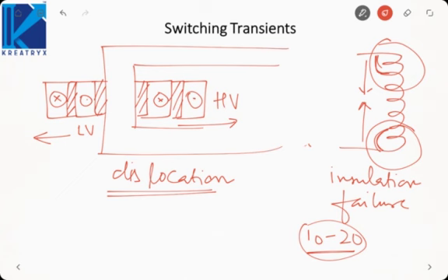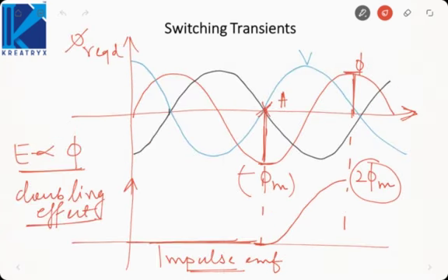Okay. Now, if you see, if we switch on the transformer when the voltage is maximum, where the voltage is maximum, this blue one is the voltage. So, voltage is maximum here. Here the flux demanded by the core is 0. And as I told you, flux cannot change instantly. Initial flux was also 0 and now the requirement is also 0. So, it will easily be able to follow the waveform of the flux and the maximum value will again be phi m. Okay, that means there will be no doubling effect observed.